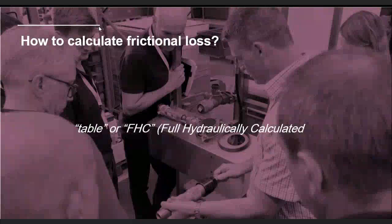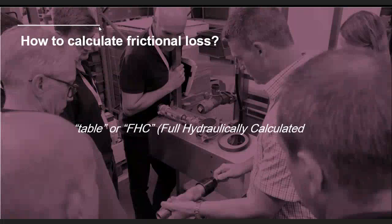How do we calculate frictional loss? Well, as I mentioned a few times already in these presentations, there are two main ways of doing this. What we call the table or pre-calculated method, or FHC, full hydraulically calculated. The difference being, table or pre-calculated is a good way of describing it. What we're using is basically half of the job has already been worked out. So we can just add in a few particulars from the project that we're working on, and we will get a reasonable answer, or a compliant answer, based on the calculations that have already been done in advance using various assumptions, which all mean that we get a suitable answer.